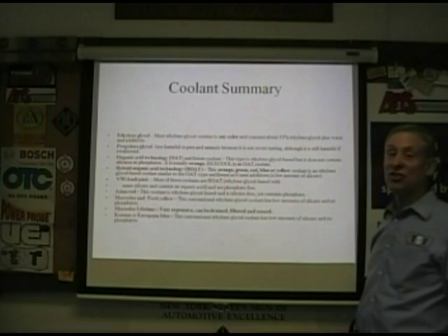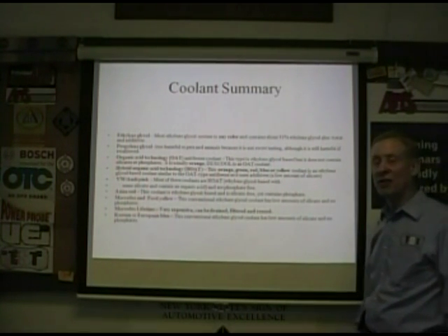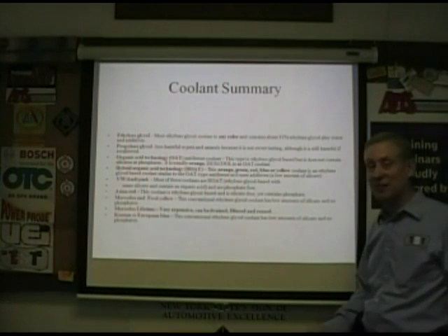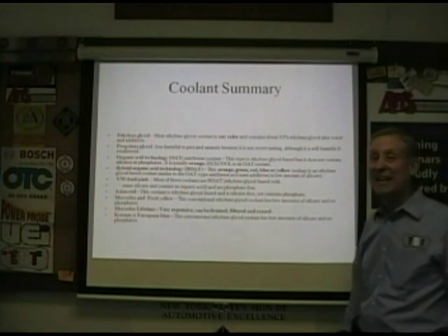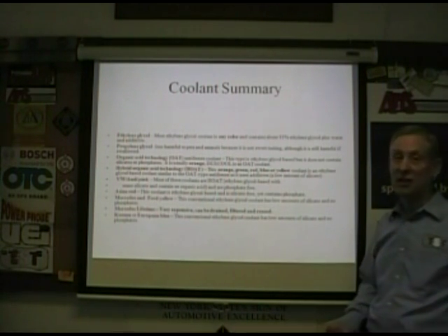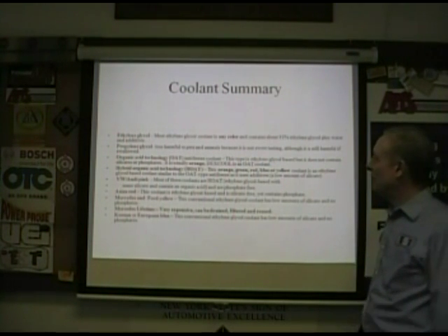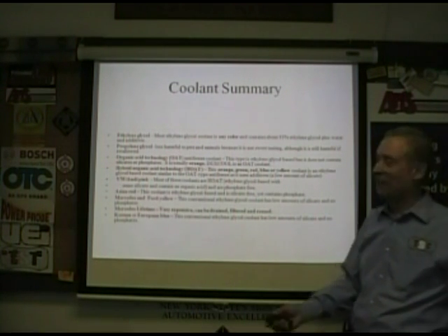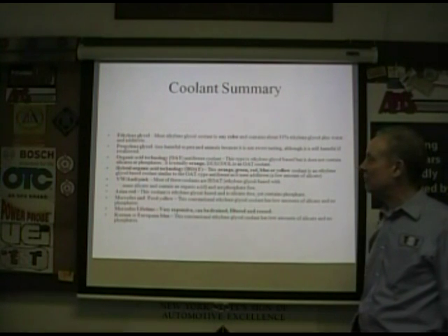All right, here's a summary. Ethylene glycol, that's really what's in all the OEM fills. Propylene glycol can be sold to you by some salesman, and it's really not recommended. I don't recommend it at all. It can't handle the heat, for starters. Less harmful to pets. They tell you it's not toxic at all. Give me a break. It's a chemical. It is harmful. OAT was the old technology, the green stuff, Prestone from the 70s, whatever. Hybrid is kind of the new dominant technology.